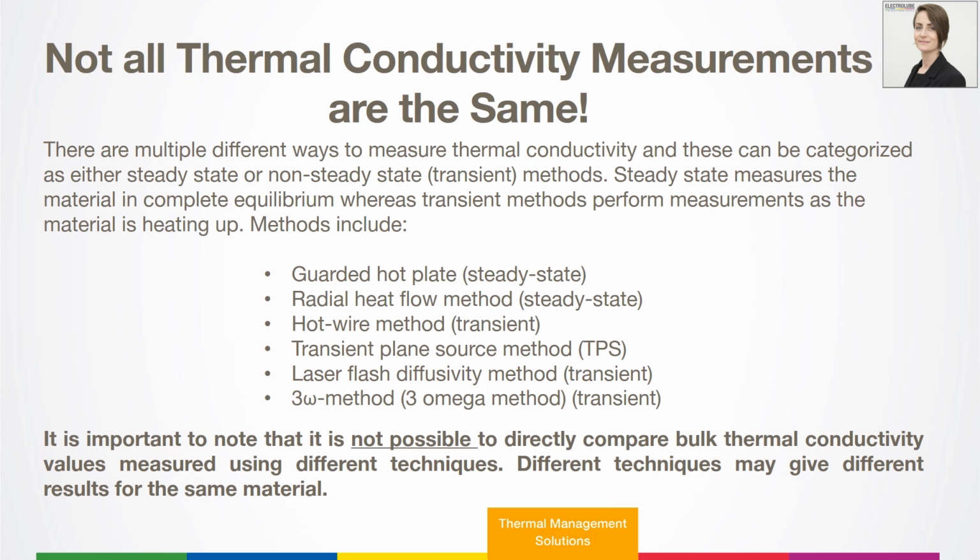Because of this, we do advise to exercise some caution when comparing thermal conductivity values on datasheets. They're there as a guideline. You can request for materials to be tested using the same equipment, or you could use them just as a starting point to give you an idea of what level of thermal conductivity you may need, and then go further with testing on your actual unit.